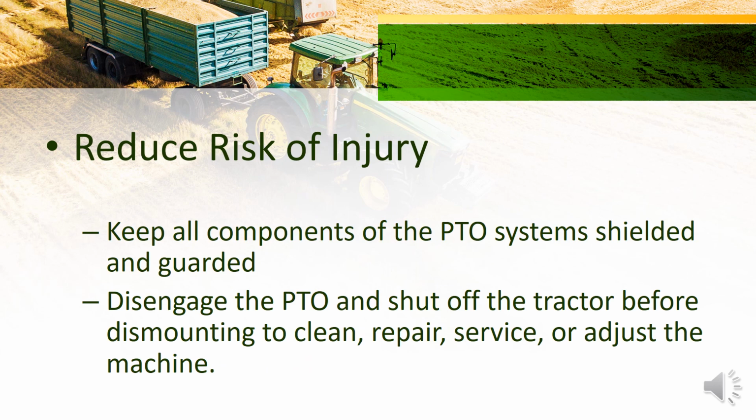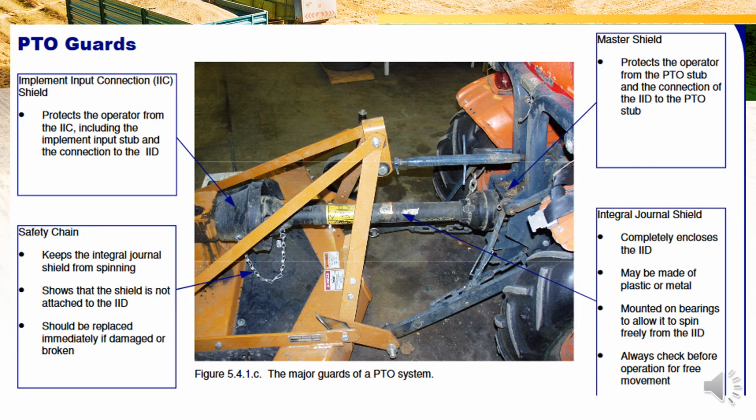So to reduce your risk of injury, keep all components shielded and guarded, and disengage the PTO and shut off the tractor before dismounting to clean, repair, service, or adjust the machine. And here is a diagram of your PTO guards.